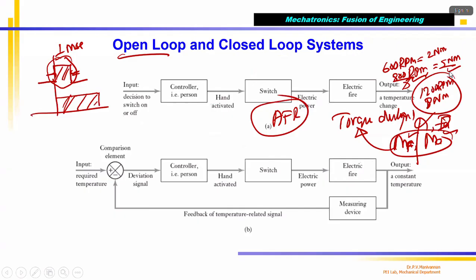Now, you develop this with 1 millisecond, all these things, because the mass of the air depends upon the temperature of the air, atmospheric temperature, right? It also depends on the altitude where the vehicle is, correct? At higher altitude, atmospheric density, air density reduces. When temperature increases, air density reduces. So if I suck 100 cc air at 30 degrees, the mass of the sucked air, say, I say 10 milligram, correct? I am talking about weight, or 20 milligram.